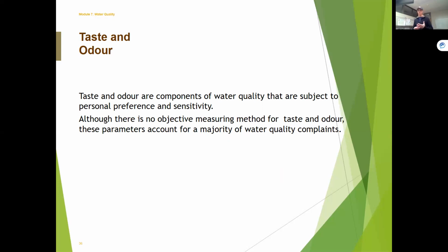But there's certain things you got to remember when we talk about taste and odor. Really pay attention to what the taste and odor could be. It's a grassy, fishy smell. It could mean maybe too many organics in there, or a stagnant line. If it's chlorine smelling like a swimming pool, it could be lack of chlorine or not enough oxidation by our disinfection process. Maybe it tastes like a medicine-y taste, and it could be from algae, right? So these are the things that are really important to understand. What is the taste and odor? Does it smell metallic? What's the issue? That's really important to figure out what it could be.